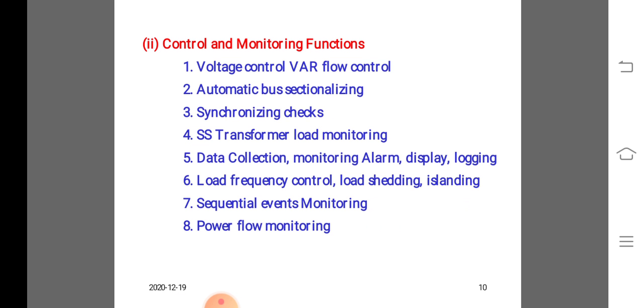The form of communication required for SCADA is telemetry. Telemetry is a measurement of a quantity in such a way so as to allow interpretation of that measurement at a distance from the primary detector. The distinctive feature of telemetry is the nature of the translating means, which includes provision for converting the measure into a representative quantity of another kind that can be transmitted conveniently for measurement at a distance. The actual distance is irrelevant.